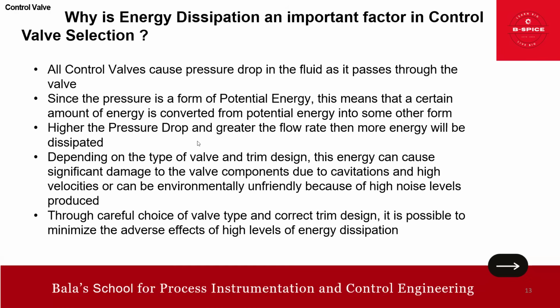So the higher the pressure drop and the greater the flow rate, the more energy will be dissipated. Depending on the type of valve and trim design, this energy can cause significant damage to the valve components due to cavitation and high velocity, or can be environmentally unfriendly because of the high noise level. Through careful choice of valve type and correct trim design, it is possible to minimize the adverse effects of the high level of energy dissipation. So energy dissipation is a very important factor.